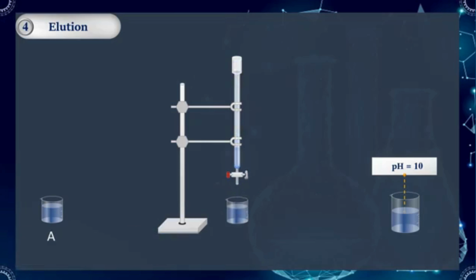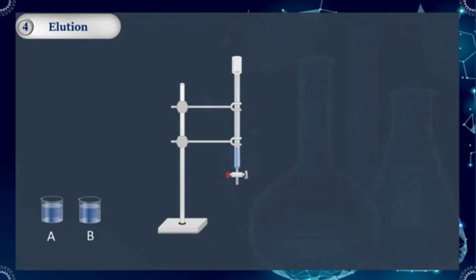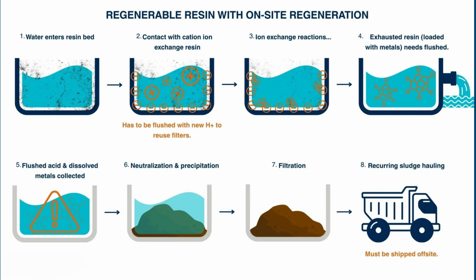A resin used for routine water softening may have a very different regulatory profile from resin loaded with chromium, arsenic, PFAS, radioactive isotopes, toxic metals, or hazardous organic compounds. EPA guidance specifically notes that exhausted resins containing removed contaminants may require special hazardous waste handling.